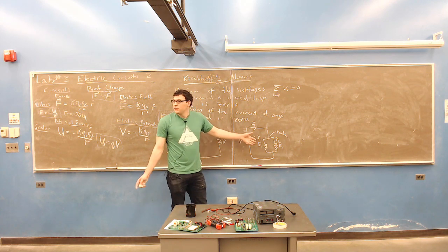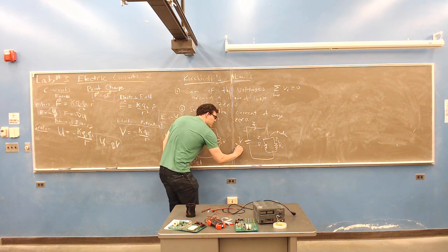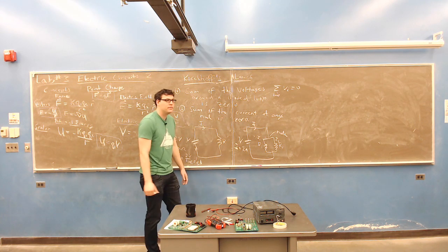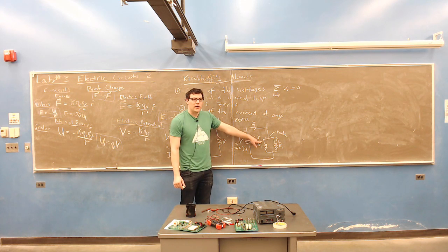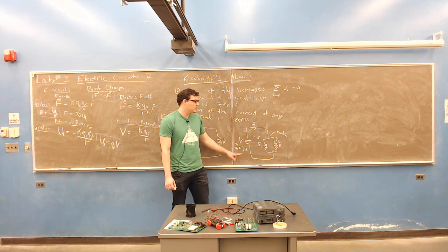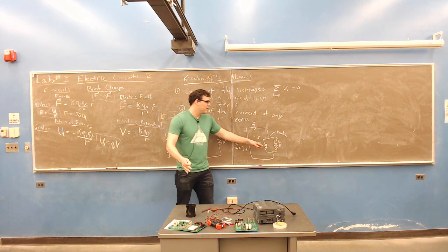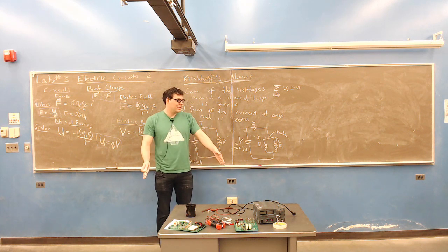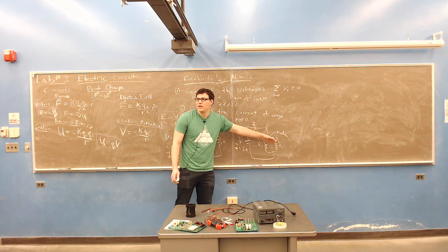Equal resistances, just to make it simple. And this current here was 2 amps. What should I1 be then? If the total current coming into the node is 2 amps, and these are equal resistors, the current is going to split. And since they're equal resistance, they're going to split equally. And so we're going to have 1 amp over here and 1 amp over there.